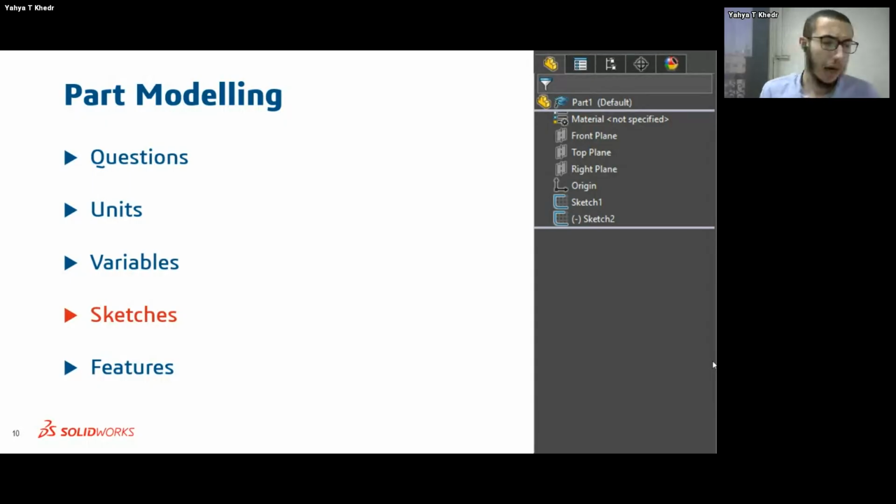So I sometimes actually do this. I go by and count how many dimensions are in the question. So let's say I've got a drawing view. I'll count the number of dimensions and then count the number of dimensions I have inside of SOLIDWORKS and make sure I've got all of them right. This is the way that works for me. Maybe it would work for you. Whichever way you prefer, just make sure that your sketches are fully defined.